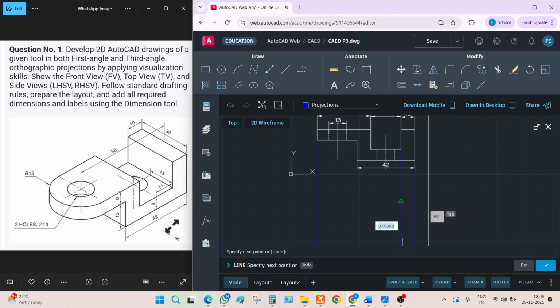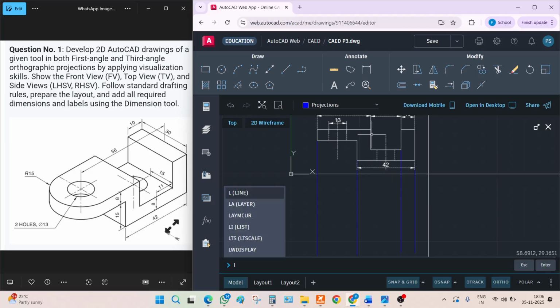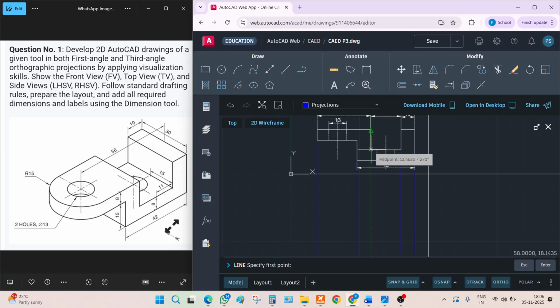All my projections are straight lines. Why? Because I have turned on this ortho option here. Under this option you can start and you can have straight lines. So from this corner also we can have one more line command. Go to this line, just move your mouse here, then press here, then enter.